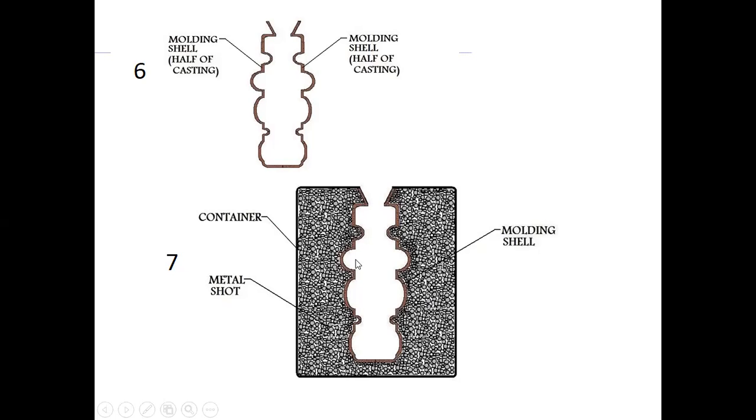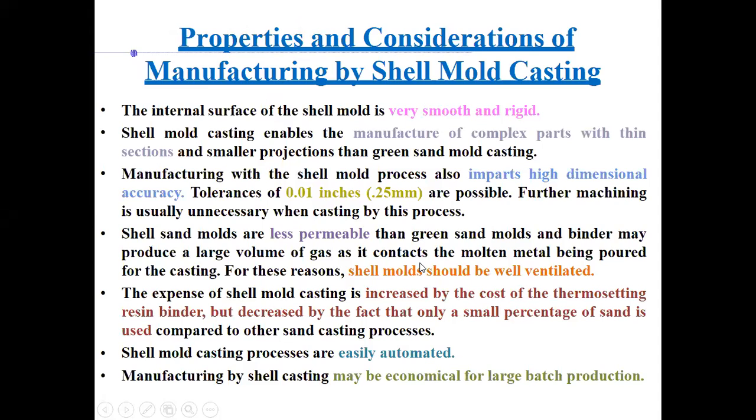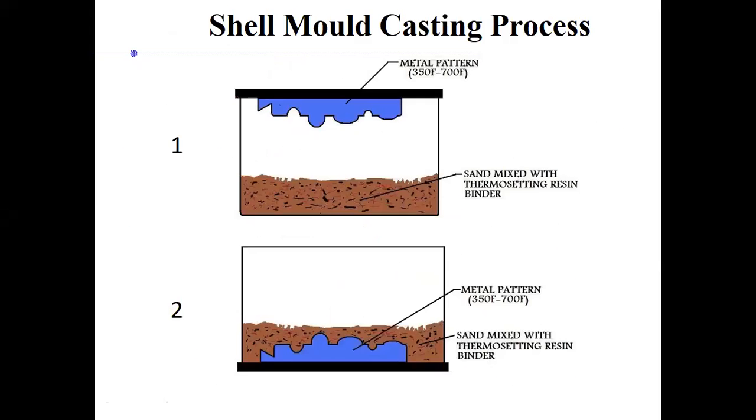It is only there to support, because of the metallostatic pressure from the molten metal you poured in, this backing material will support this shell all throughout. When the molten metal is poured, it will support this backing material. That's what the purpose is. Now I hope the process is clear. Any doubts?